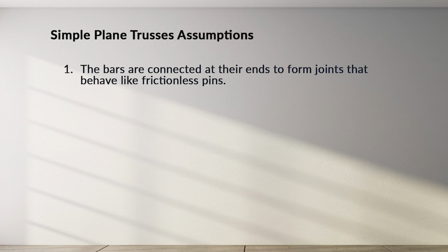This first assumption represents a substantial departure from the real truss. The ends of the members are attached to each other so that bending of the member must occur. The forces in the members calculated based on pin construction do not differ substantially from their true value.